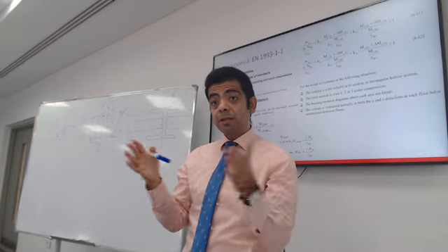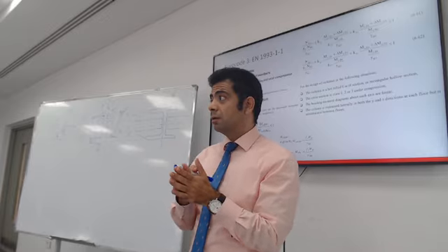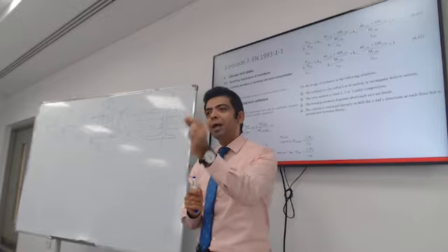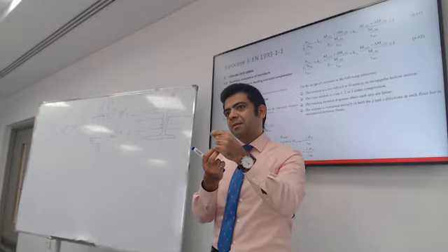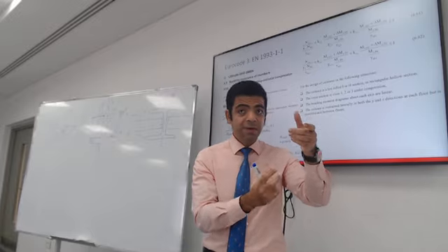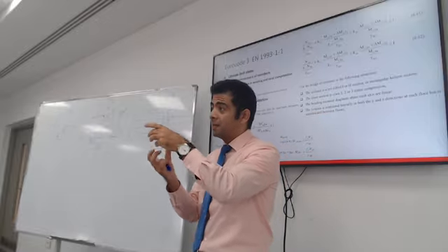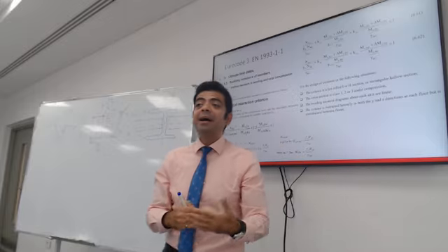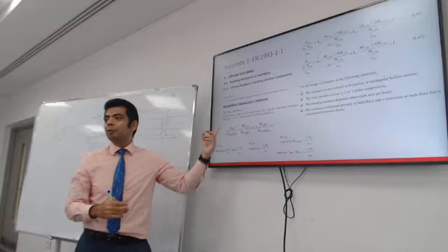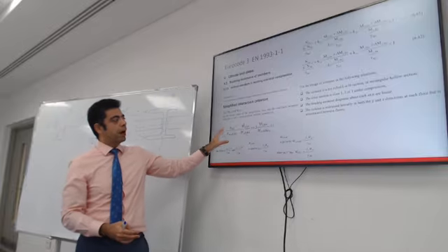Okay. You're gonna add just the moments? The moment over the capacity. You add the ratio between the moment and the capacity, the actual moment and the capacity in that direction. And then you add to it the actual moment and the capacity, and then you add to it the actual normal force and the capacity normal force according to this equation.